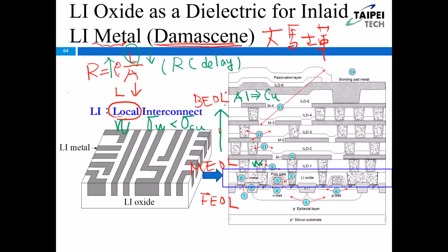Okay, so the next step, after I have the pattern for SiO2, I electroplate the copper. After we electroplate the copper, you see how the profile is high, low, and high, low, right? So how should we do? We use CMP, copper CMP, so we can remove the copper layer by layer. So right now we use the CMP to remove the copper layer by layer.